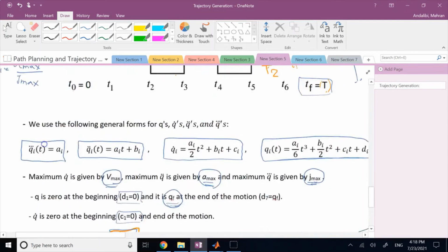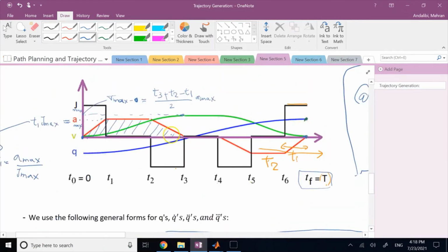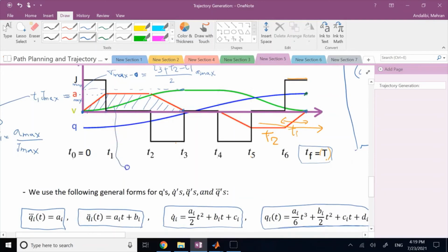Where do I get this one from? Well, that comes from the fact that your acceleration goes from what? 0 to 0 during this trapezoidal motion. And you know the change in acceleration during the very same time between 0 to T3, which is 0 minus 0, correct? Final value minus initial value, comes from the integral under the area of the jerk, which is this area here in green. And what is this area?